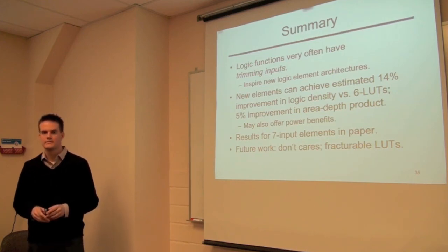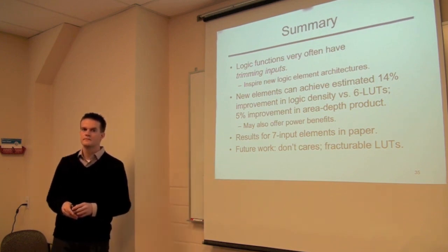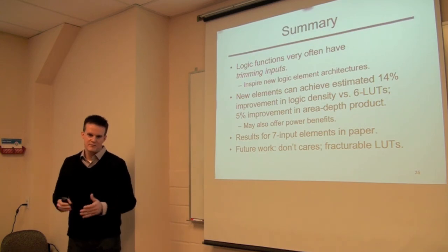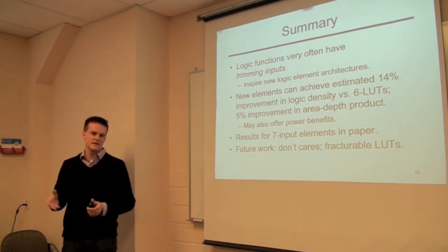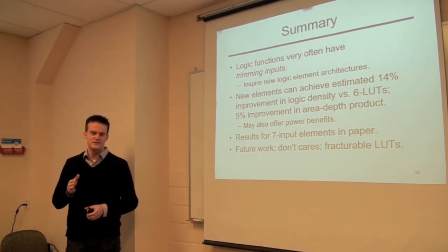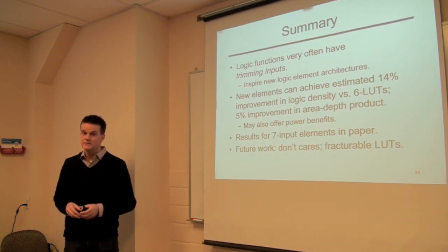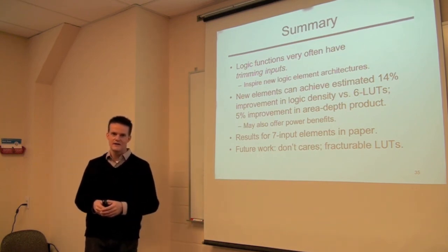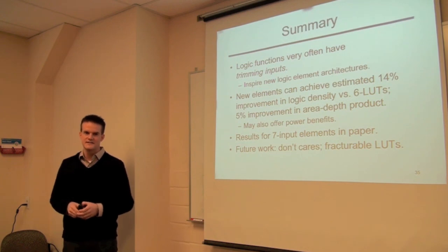Brayden: All right, a question from the chat room: what's the runtime hit of the cut pruning step? We didn't even measure it. It's almost the same runtime as without the cut pruning. So it's very fast to find these trimming inputs. You're doing a fast traversal of the AND-inverter graph, and then you're basically marking some AND gates as out of it, and then for what you have left, you see how many input variables you have left in it. So it's not a significant runtime hit.